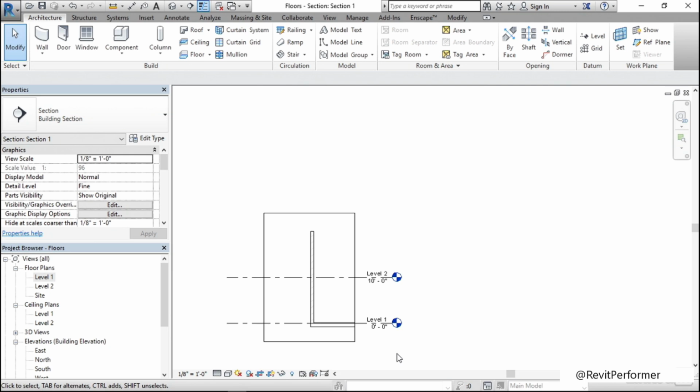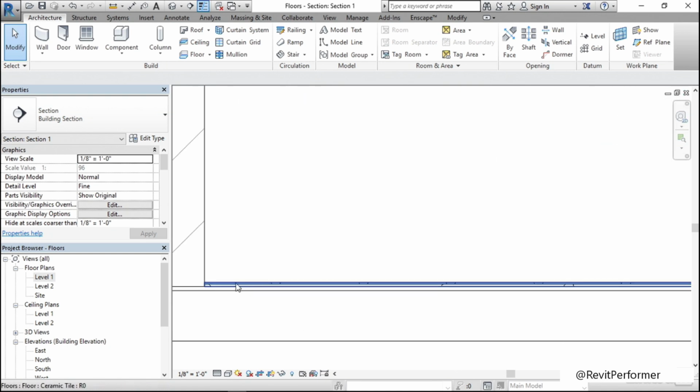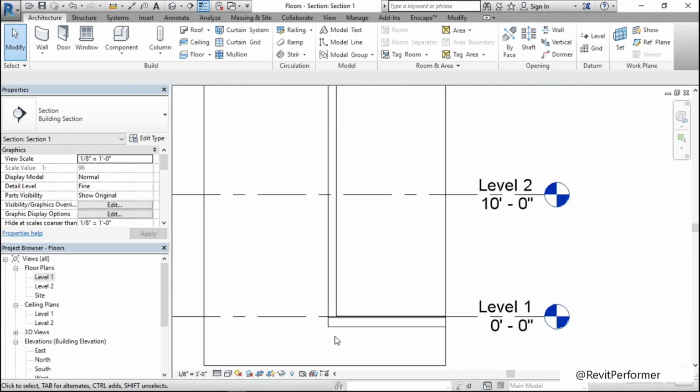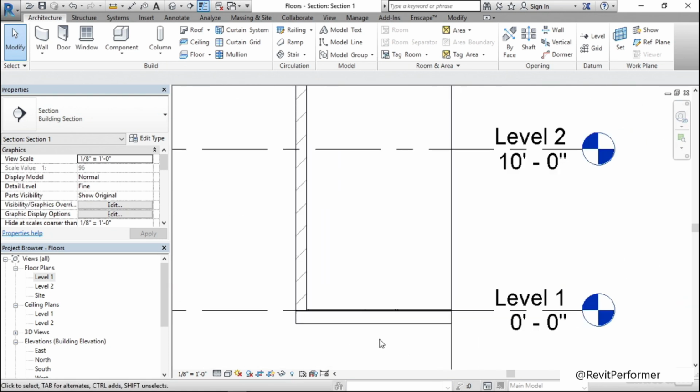This is actually my own personal favorite way to apply material finishes to floors. Have a structural floor and then come back later and apply an actual floor finish floor there inside of each of the spaces. That also means that if at some later time your client decides, I want to make a change to that flooring material, all you need to do is select on your finished floor, exchange that out with appropriate floor type, and then without adjusting the structural members of the Revit model at all, you can then change the floor finish on a room by room basis.